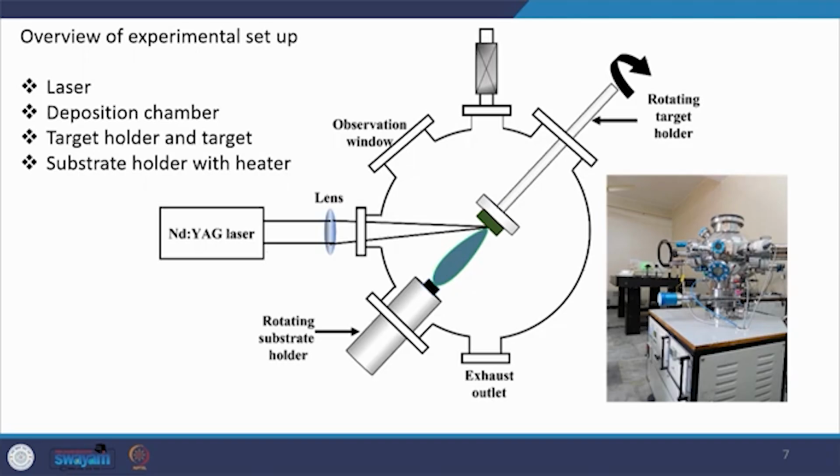of the plasma. One can do this by spectroscopic measurements of whatever species are coming from the target. One can analyze those species, their velocity, and the temperature of the plasma. Sometimes one can monitor these in situ while depositing the thin films.